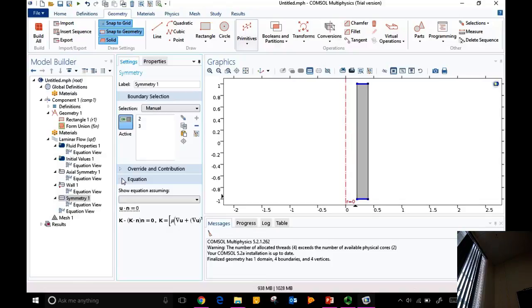Tangential component of the stresses are dependent on the velocity gradients in the other direction. So the velocity gradients are 0. The velocity is 0, the velocity gradients are 0. So there is really no forcing from the two ends. Okay? Any question on that? So this is really, we are talking about tight coupling and developing a feeling for how fluids move and how we simulate those.